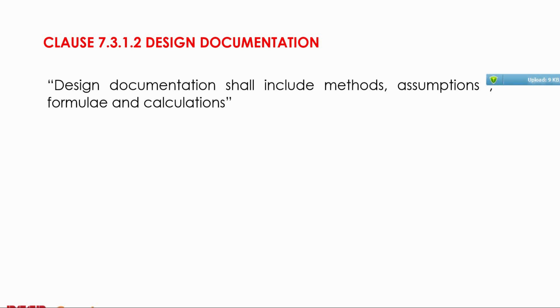It starts off with a concept, then the inputs and outputs are defined, along with the calculations to verify the design and also the validation methods used. Any changes to design must have design reviews documented throughout the design's life cycle. Finally, it must be released for manufacture with the necessary sign-offs. Often the design and manufacturing phases run concurrently these days. When they do, it is even more important to have auditable controls in place.